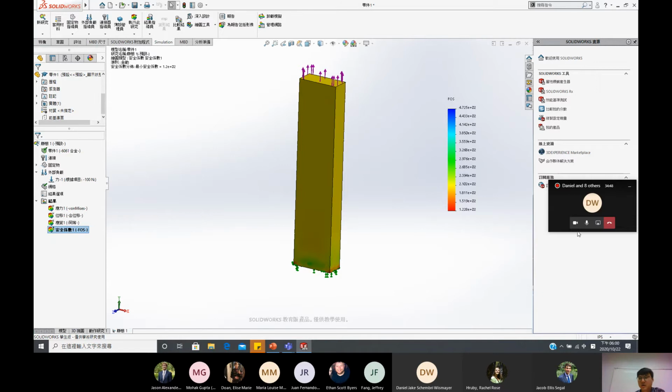I mentioned, just to give you a heads up, that usually in the industrial sector, when I design, a factor more than 6 or 10 is already pretty much safe. Over here it has a minimum number of like 100, 1,000-ish. You can see the factor of safety over here is like 1,000-ish. So this is very safe for the load that we're applying right now. So you don't have to worry about that. And then other stuff we can do is